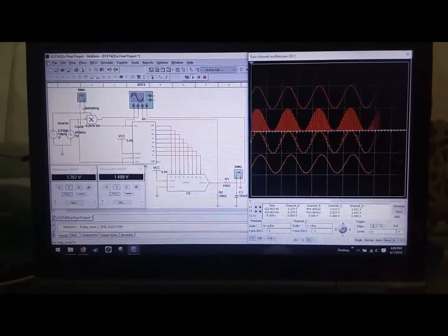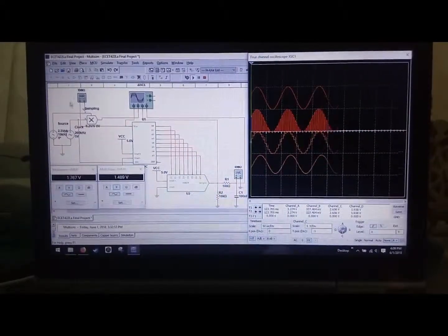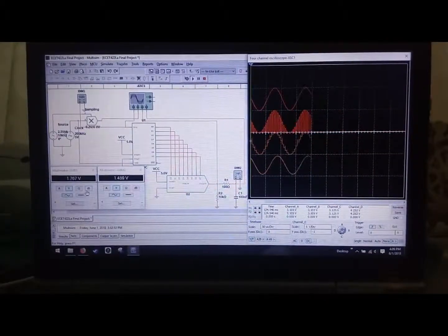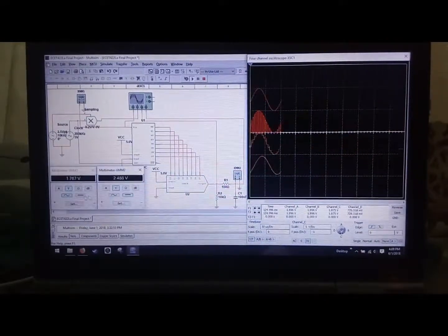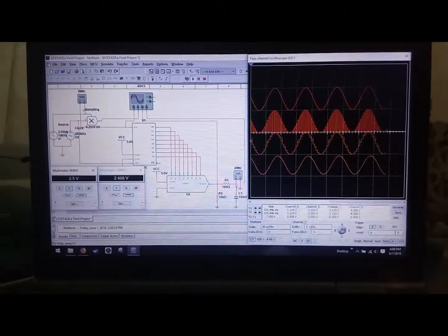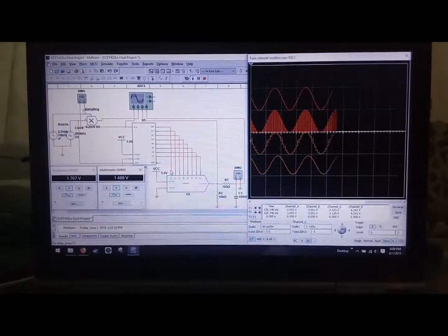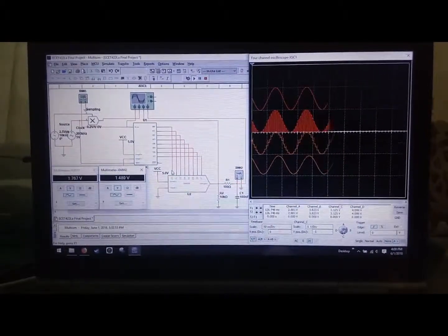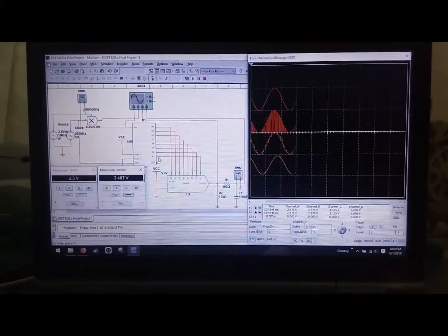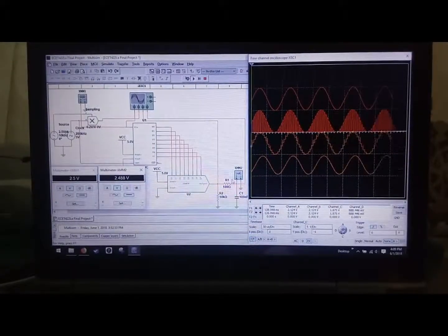We see here in the start of our circuit and in this end of the circuit that we have two voltmeters. This is to monitor the AC voltage and the DC voltage of our output and input. The AC voltage is to monitor the effect of aliasing, while the DC voltage is to monitor the effect of quantization error.